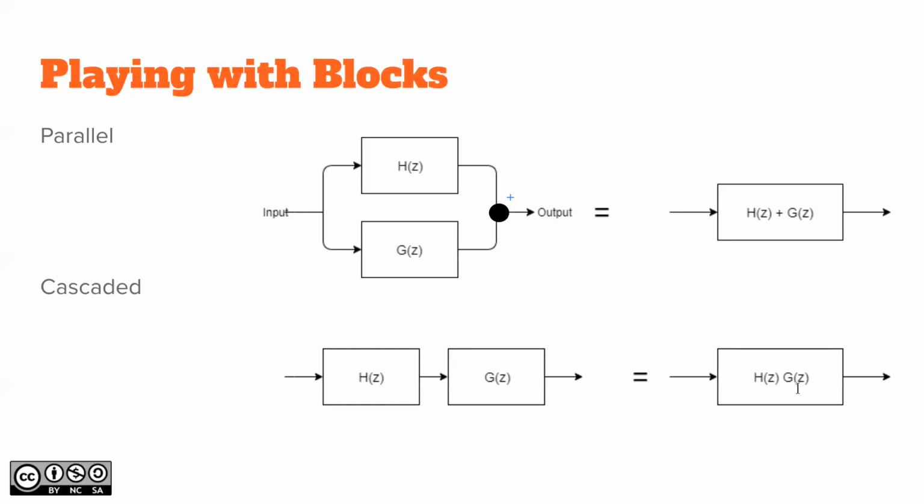In analog filter design, with one single operational amplifier, you can do a Sallen-Key filter, which is a second order filter. So in order to make higher order filters, you cascade these blocks, and each of those has its own second order transfer function.